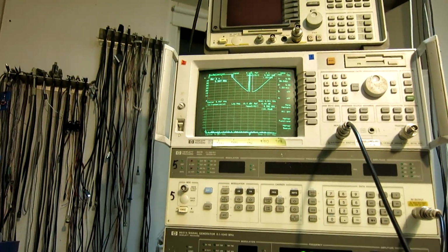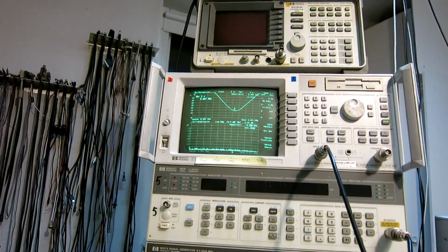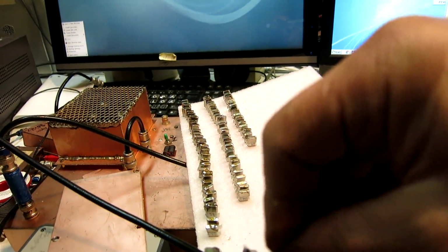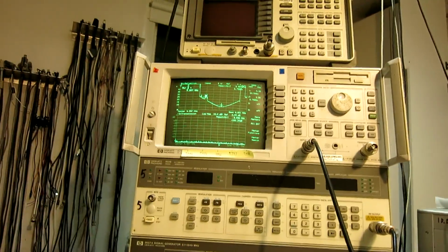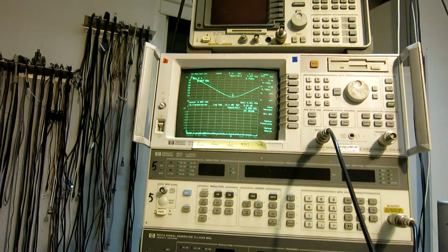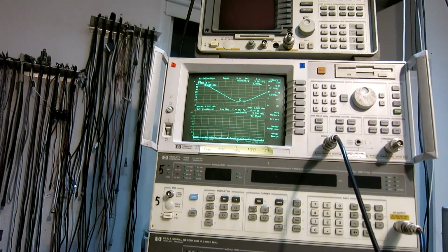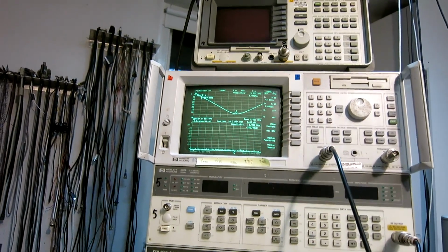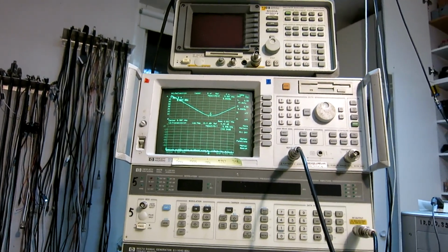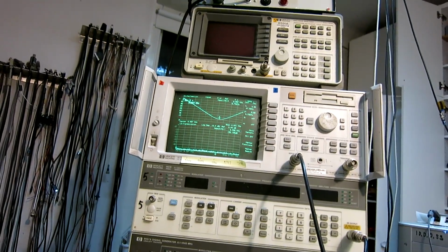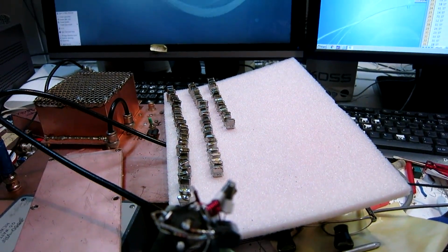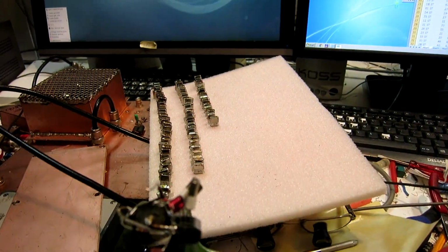as happens, I get precisely the same resonance frequency. So now I can connect both these in parallel, like that, and hope to see a nice curve with the parallel resistances of those two. It now says something 6 ohms, but I haven't calibrated this properly, so don't trust the absolute values of the resistance. But it shows that this is the way to compensate for small differences in crystal resonance frequencies.